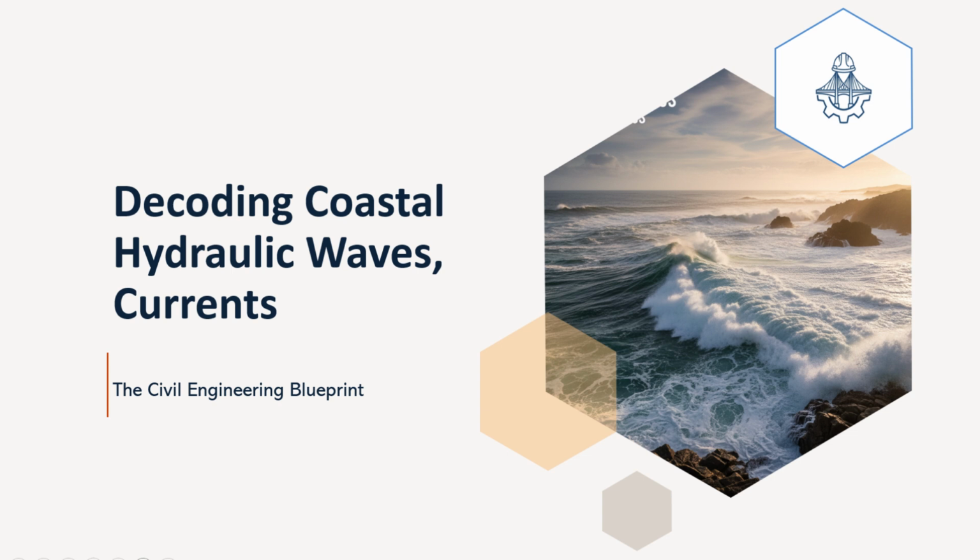Finally, for this section on transformations, as waves reach their ultimate limit, they break. So let's briefly revisit wave breaking criteria and understand that crucial point of no return for a wave. This is obviously a critical factor for shoreline protection and design loads. Absolutely. Most commonly near coasts, we deal with depth-controlled breaking. As wave height H continues to increase during shoaling, and possibly refraction, it eventually reaches a critical limit relative to the local water depth d. The wave becomes too steep to support itself.